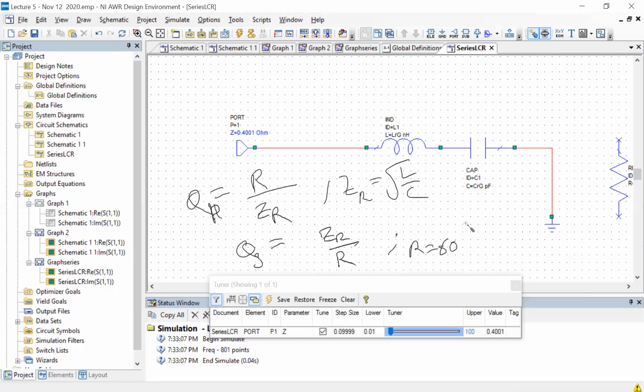Typically we use transmission line based resonators, and that will be the subject of the next lecture, where we'll continue with resonators, but now we will move to figuring out how to make them using sections of transmission line. This is basically the closer analog to the Fabry-Perot type of things, where you have a medium where light can travel and you put two mirrors on either side. And again, those mirrors could be capacitors or other things, which I'll discuss next time.